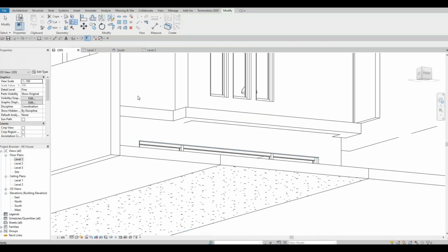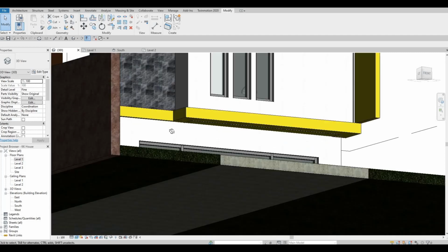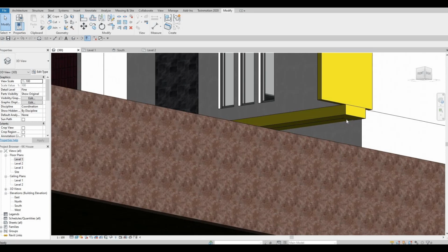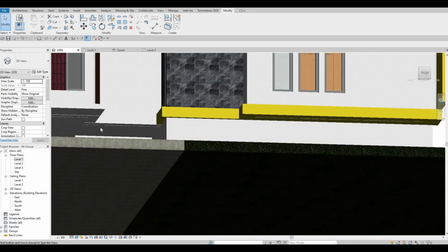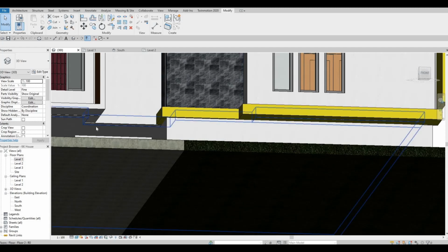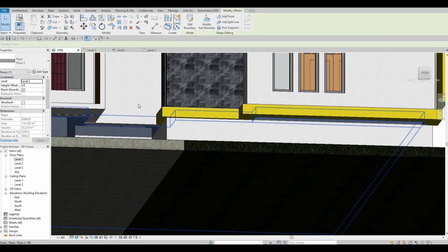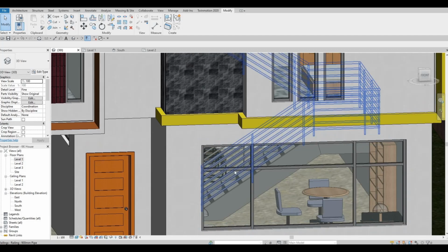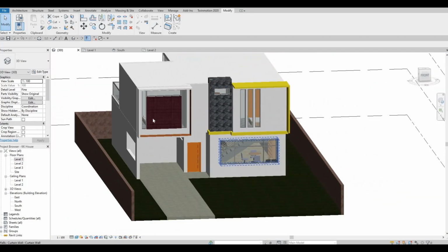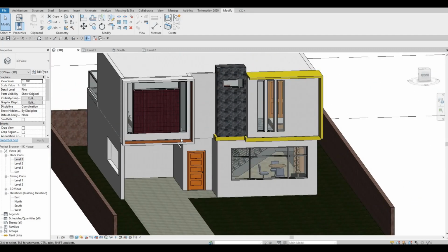And now I could select that, and if we double check with realistic, as you can see, this is the same material as that, but the remaining of the floor is similar to this, which is gypsum wallboard, so white. So it's good to know how to split faces, especially with extrusion and with this.